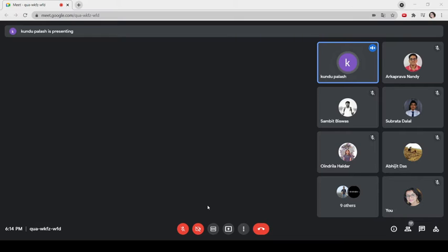So the split timer mode gives the programmer the facility to operate two timers in 8-bit mode. And there are two timers, timer 0 and timer 1. That means in effect, 4 independent timers are possible under split timer mode. So each timer mode of operation has a significance. This is very important. Now what is the significance of C stroke T? Counter stroke timer. I have described the operations of the timer.